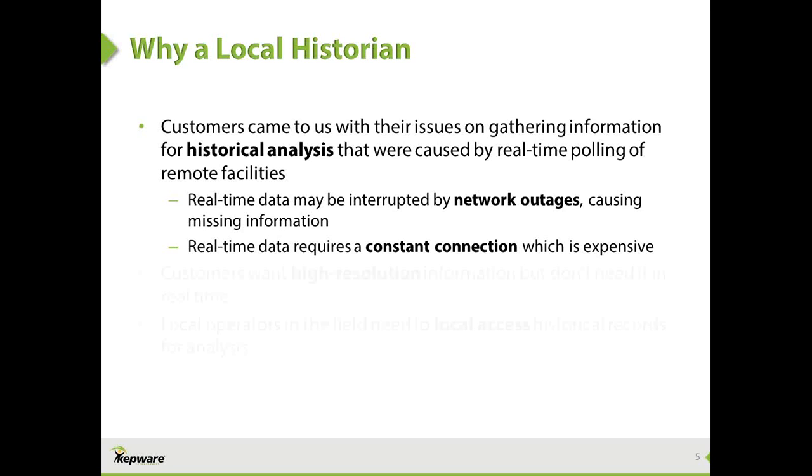The other thing is that customers still want really high-resolution information, so they still want to see this information every second or in the millisecond range. And local operators in the field need a way to easily access that information for analysis. That behooves them to have this local data store that they can access with that high-resolution information without worrying about a network connection. So posed with that request, Kepler developed the local HDA historian plugin.